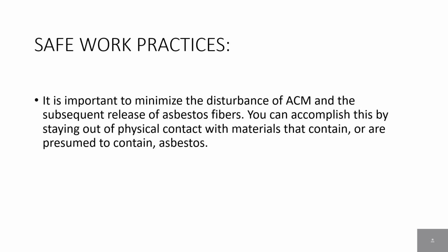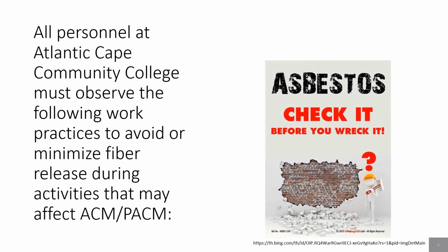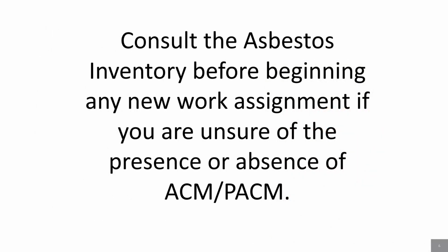Now we're going to discuss some safe work practices, which are important to minimize the disturbance of ACM and the subsequent release of asbestos fibers. You can accomplish this by staying out of physical contact with materials that contain or are presumed to contain asbestos. All personnel at Atlantic Cape Community College must observe the following work practices to avoid or minimize fiber release during activities that may affect ACM and PACM. First and foremost, consult the asbestos inventory before beginning any new work assignment if you are unsure of the presence or absence of ACM or PACM.